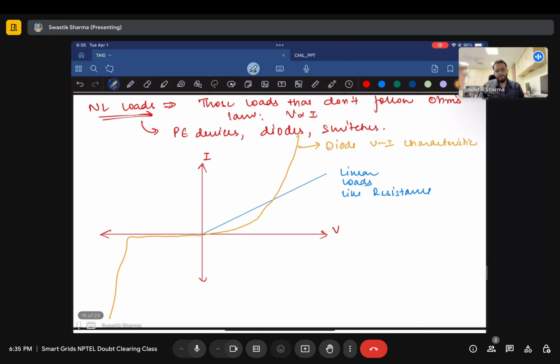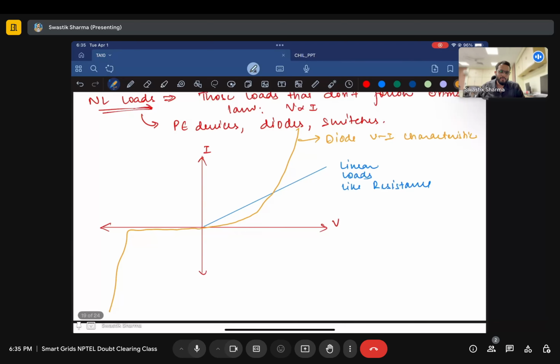So now you can say, okay, diodes and all these power electronic converters produce harmonic distortions, but still we use them, right? Why do we still use them? It's just because the benefits outweigh their cons. They make the system less bulky, and by just controlling the switches, you can convert the waveform from the AC domain to the DC domain, or DC to DC, and you increase the power that you're getting as well. So you see the benefits outweigh, and that is why you then propose newer solutions.